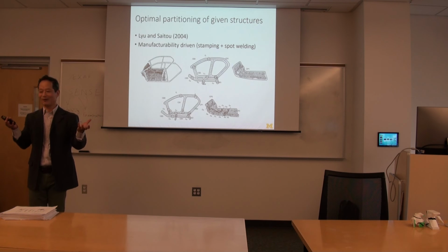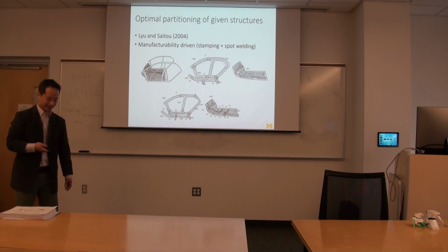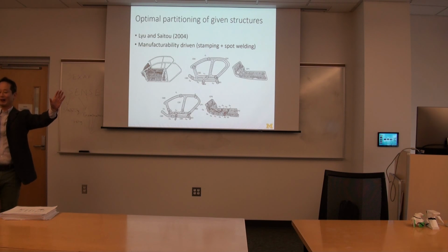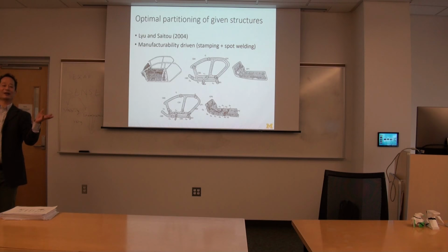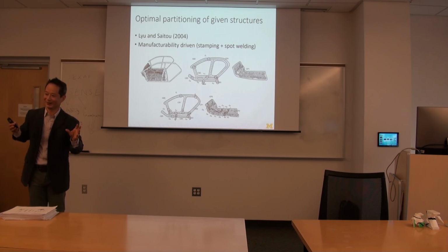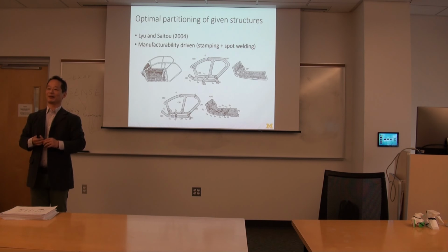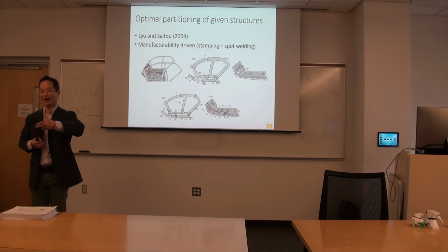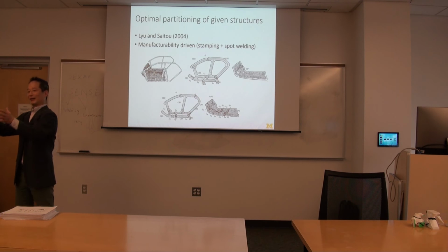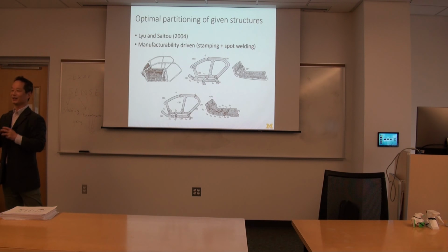one piece was designed for, which is typically some kind of structural performances which the original one piece design was designed for. You have to keep on watching the impact while you're applying the partitioning. And typically, when you partition it, your performance goes down because one piece is typically the best. But then your idea is that you will cut into pieces in such a way that the negative impact to the overall performance is minimized while you are satisfying the manufacturability of each cut component.